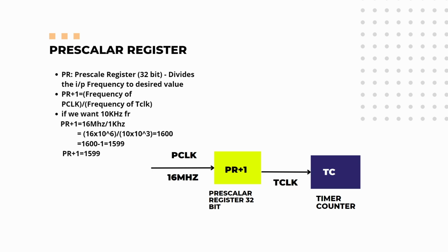While we are doing a precise timer, we have used 1 kilohertz, which means it is going to perform 1000 cycles per second. So we used the millisecond delay there. Here we are getting 10 kilohertz, so it is going to be 10,000 cycles per second. For controlling the brightness, I need a finer resolution, so for that I am using 10 kilohertz.